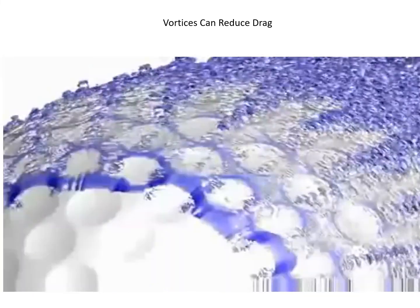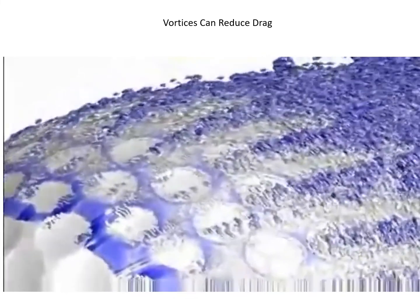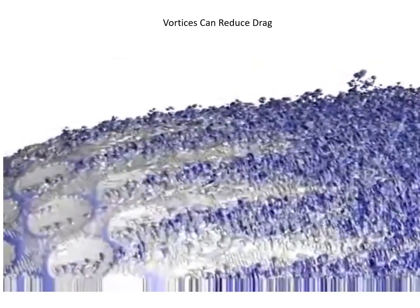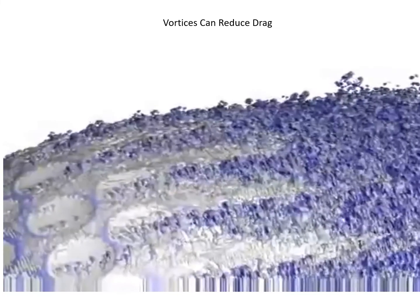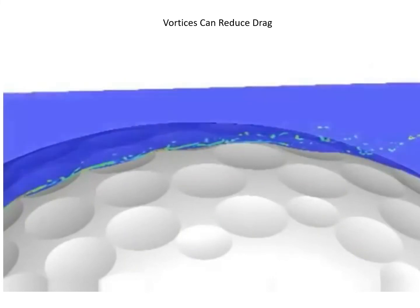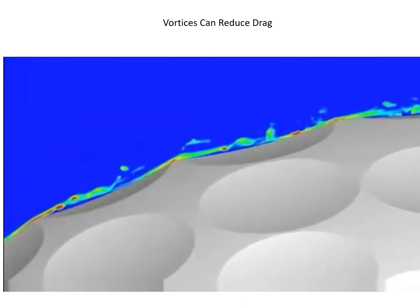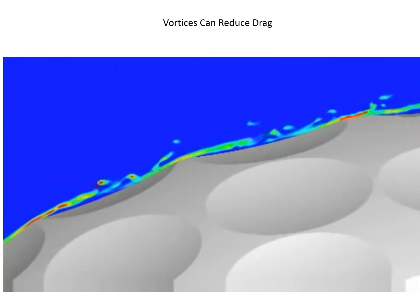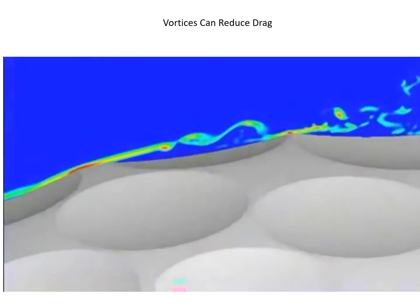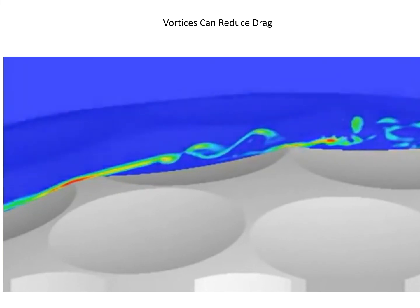Moving into about 45 degrees from the leading surface of the ball, we can see a number of trains of vortices have developed. These lines of whirlpools follow the scallops of the dimples in the direction of the airstream. Closing in now on the air's behavior around just a pair of dimples, we see the airflow evolve from front to back. Watch now within a single dimple as the air detaches and shears away, varying with the stream's direction.